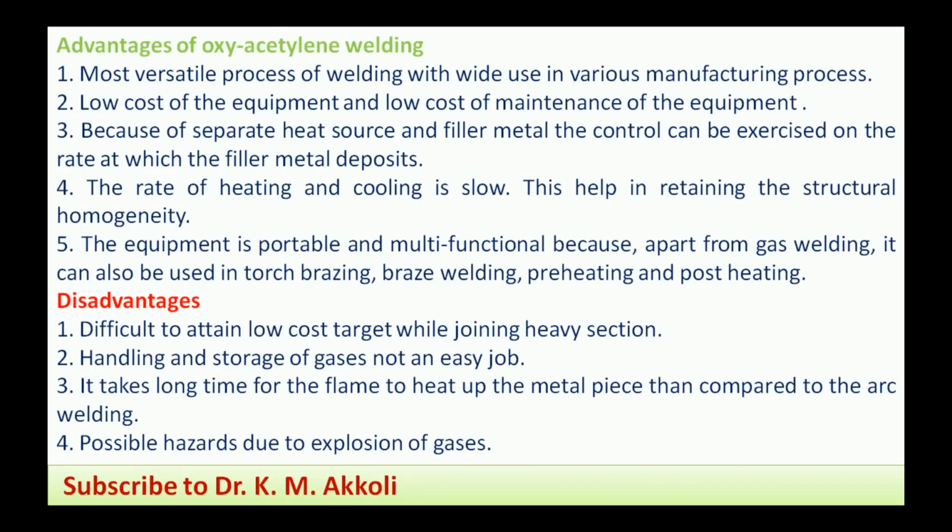Continuing with this, we are going to discuss the advantages and disadvantages of oxy-acetylene welding, or gas welding. It's the most versatile process of welding, widely used in various manufacturing applications. It has low cost of equipment and low cost of maintenance. Here the equipment means only 2 cylinders, the torch and connecting hose pipes. That's why the equipment is low cost, and maintenance cost is also lower.